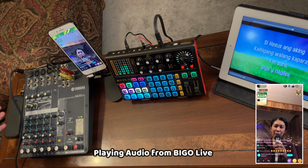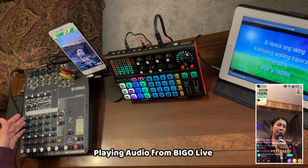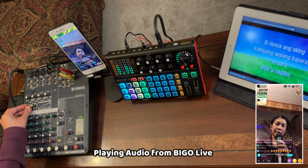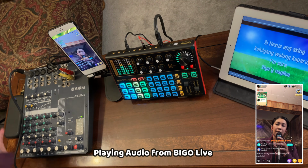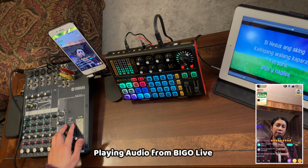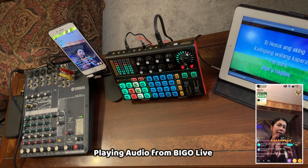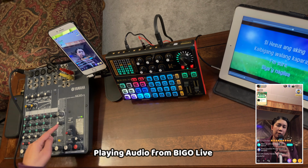And by the way, my mic settings over here on this mixer: my high, mid, and low are all at the middle. My compressor is at 9 o'clock. My gain is at maybe about 11 o'clock. And as you can see over here, my phantom power, 48 volt, is turned off. That is because I'm using a dynamic microphone, so I don't need that to be turned on. That is only for the condenser microphone.